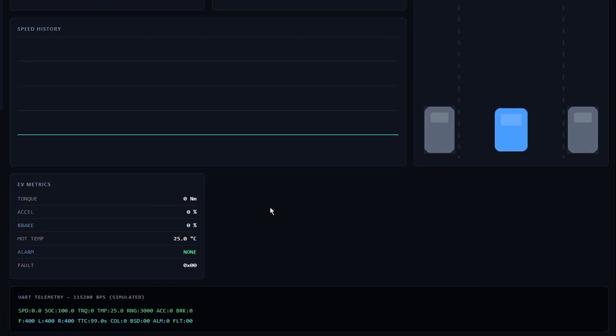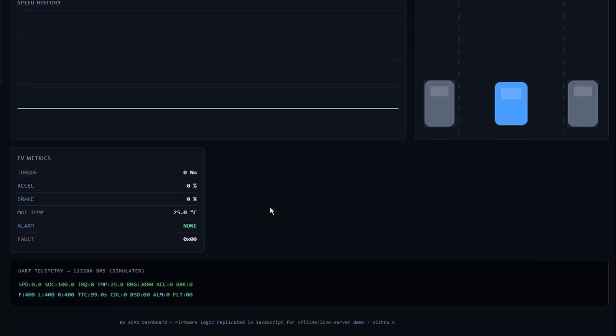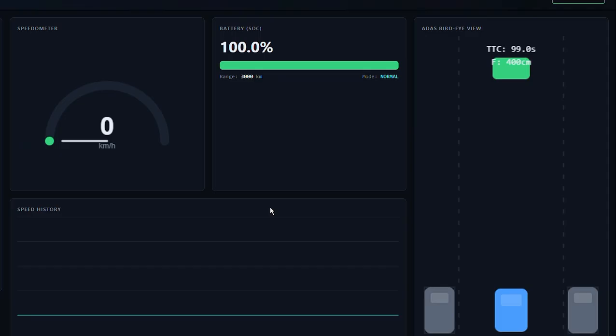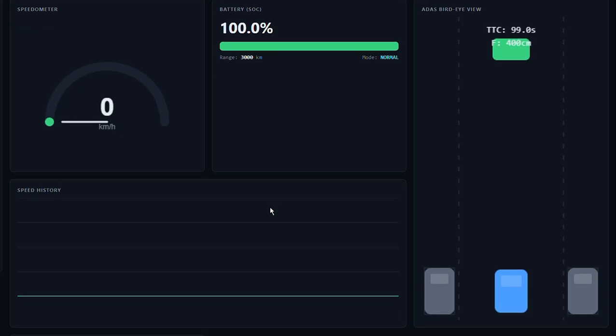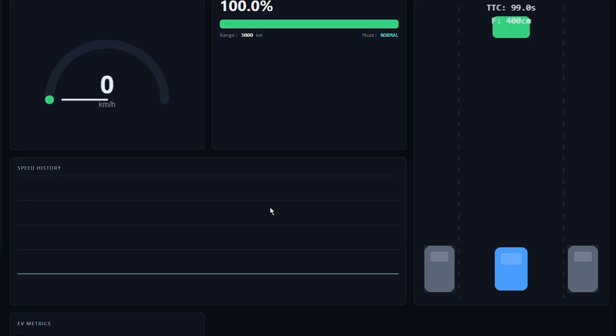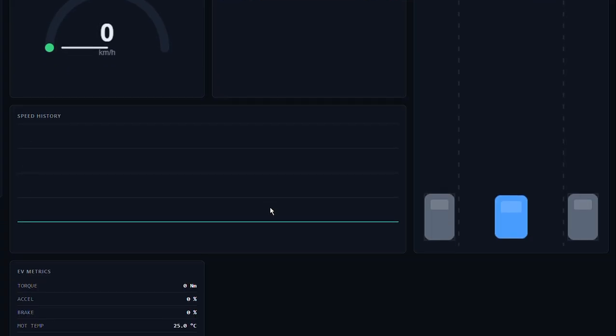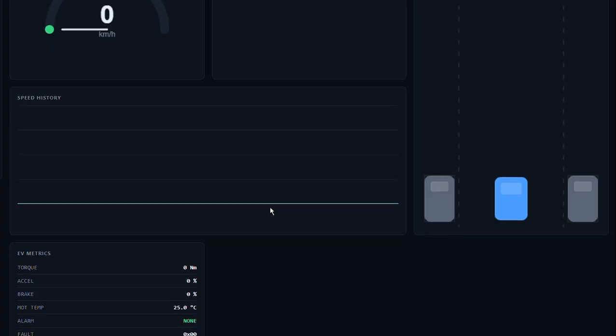So I developed firmware in STM32CubeIDE using C, simulated the STM32F103C8 Blue Pill in PicSimLab and built a live dashboard in Python using Matplotlib. So the system uses ADC, timers, and USART communication to process sensor data and transmit real-time telemetry. So now let me show you the system architecture.